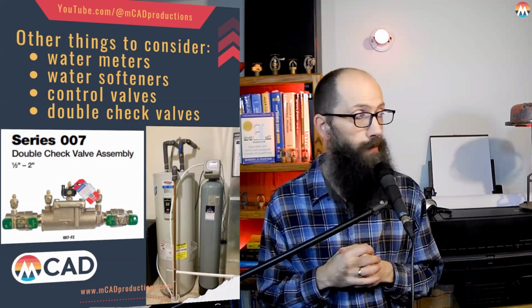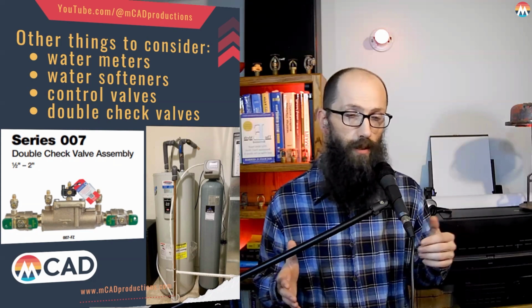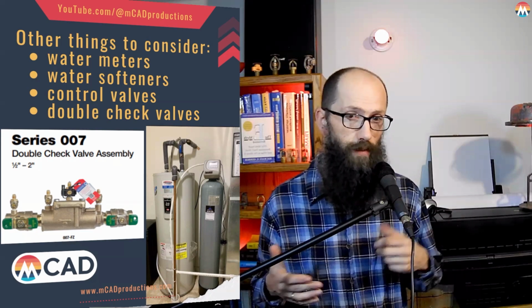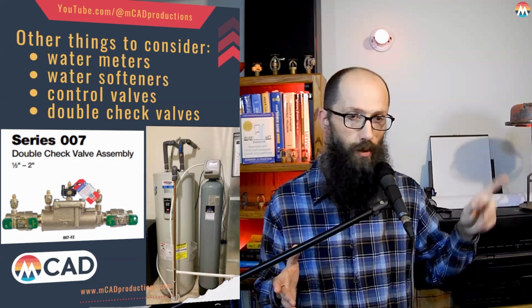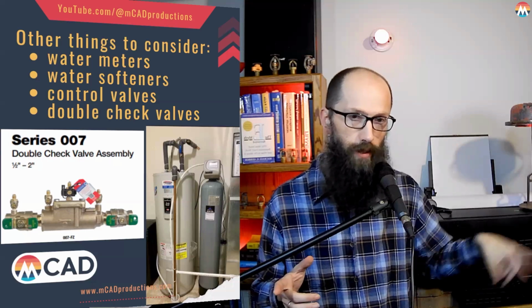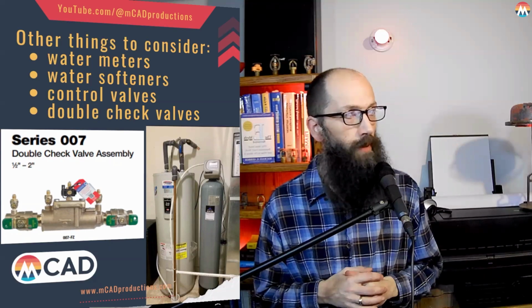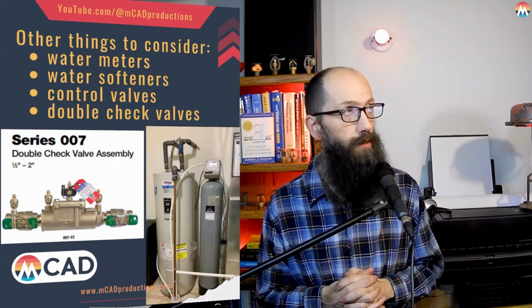I think we had some conversation in the Q&A a couple weeks ago. There are alternatives where you don't have to have the double check valve, called a flow through system, where you tie them into toilets so you always get water continually flowing through it. It can be a good idea because double check valves do require maintenance.